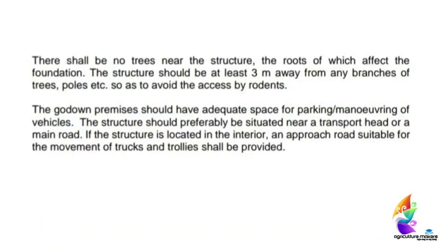And there should not be any trees near the structure, as the roots may affect the foundation. The structure should be at least 3 meters away from any branches of trees, poles and anything, so as to avoid access by rodents. And these data you have to remember.